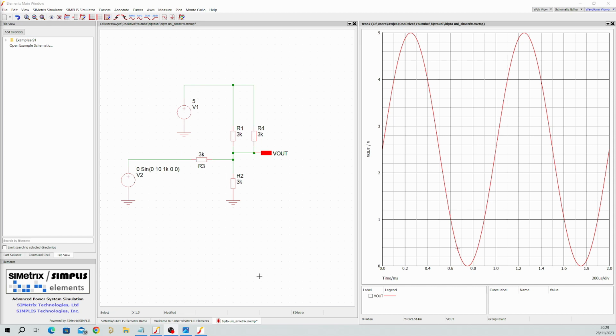So this was just a short video really based on how to convert a bipolar signal to unipolar. There are many different ratios of resistors. I obviously haven't gone into how I've picked these ratios. I could do that if anybody's interested. Just send me a comment. But you can do these for 2.5 volt ADCs, 3.3 volt ADCs, 5 volt ADCs. It's just a way of manipulating the network.